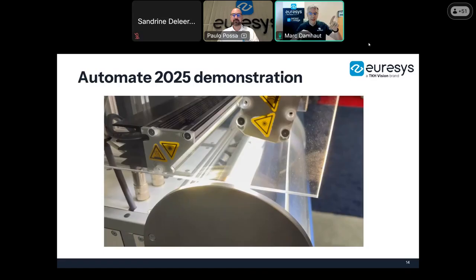It's using line scan cameras from ChromaSense and Coaxlink Quad CXP12 frame grabber in a demonstration that shows image acquisition for battery foil inspection application. You can see barely the battery foil here on the drum. And then you can see that it's using two lights for simultaneous interleaved dark field and bright field illumination.